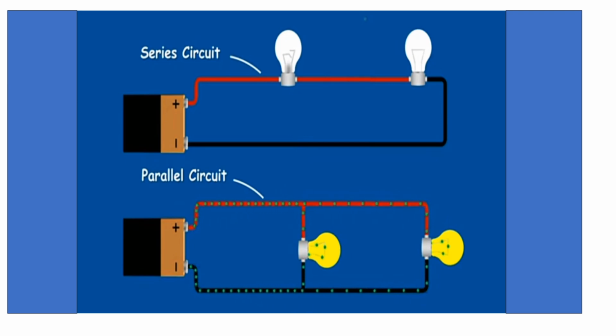Meaning, when you connect bulbs in series and there is a circuit break in one, as you can see one is off, then the whole circuit is down. So it's quite dangerous to connect these gadgets in series, for one reason: a breakdown in one bulb, in one appliance, affects the entire system.